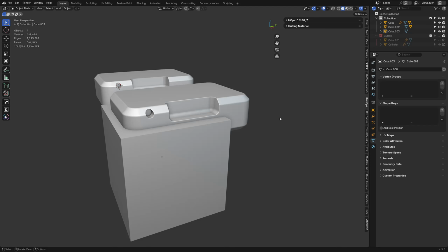Manifold's really great, but it has a couple problems. Sometimes it will completely fail to do a boolean for whatever reason. No idea why. It can sometimes distort the mesh. It's pretty rare, but it sometimes will. It'll make a flat surface not flat anymore for whatever reason. And it tends to be a little bit slower than float, but it's about as precise as exact. So it's got a nice balance, but it only works on solid mesh. You can't use it on non-manifold mesh.